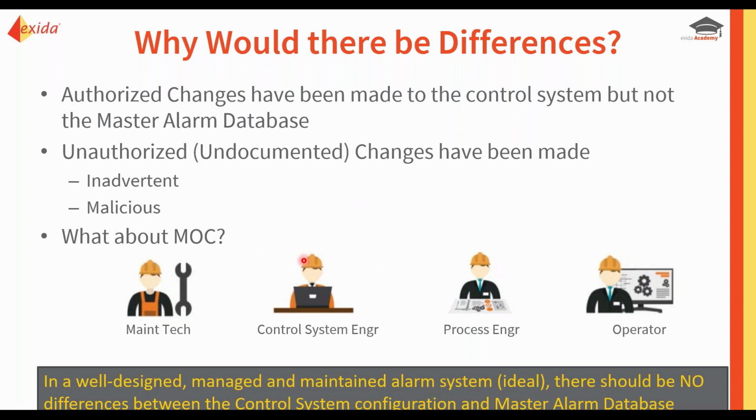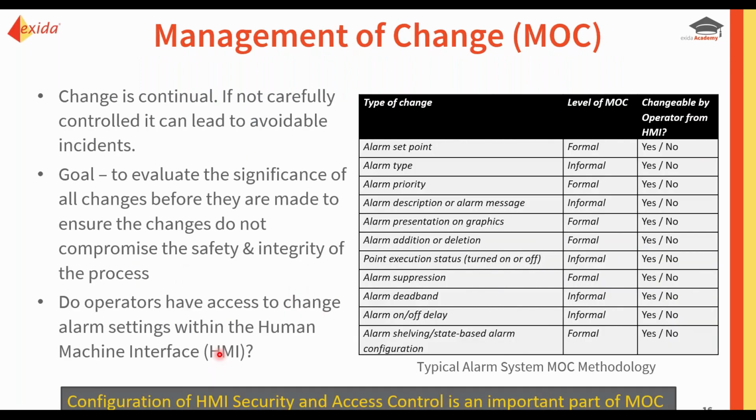So MOC is what we should go through to make sure that any change is reviewed and authorized. Now, in a well-designed, managed, and maintained alarm system, in the ideal world, there really should be no differences between the control system configuration and the master alarm database. Ideally, any MOC action that's configured in the control system would either also be configured in the master alarm database, or perhaps changed in the master alarm database first and then pushed into the control system.